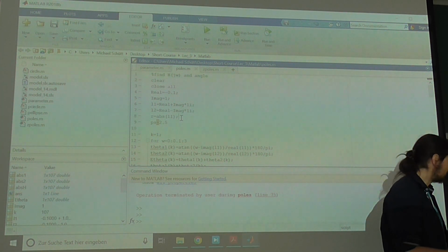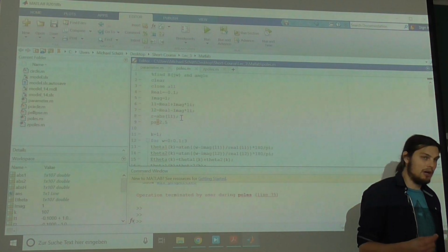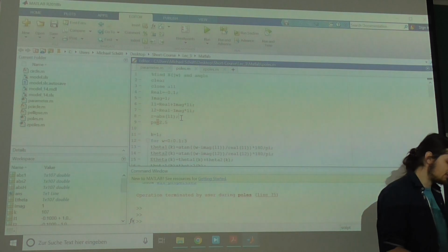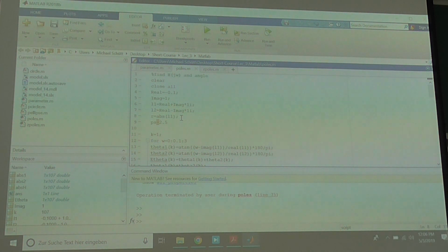What else did we learn? We learned about feed forward, and we learned about observers, right? So observers basically, what do they provide for us? What's the up and down? That would be what we see in our homework, but what do observers do for us? We get a pure signal from the impure signal. Yeah, so they basically give us cleaner signals, right? They are like a filter, but without lagging properties. So they're basically a better filter. And if we have model information, we should always use this. It's a better filter.